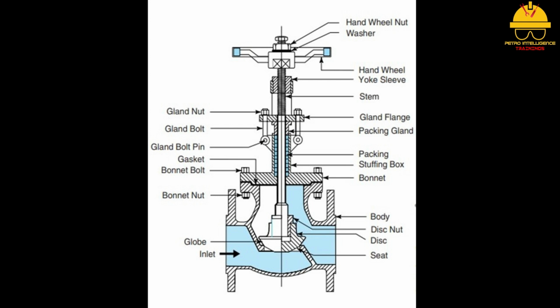The seating area comes in four designs: cone-shaped, beveled flat surface, O-ring or washer, and tapered or needle-shaped cone. The seating area is where the flow control element closes against the body of the valve to stop flow. The seating area can be replaceable or fixed. Seats must provide a clean mating surface to the flow control element to seat properly. The seat can be fabricated or cast as part of the valve, press fit, threaded, or welded into place. High temperature and high pressure situations may require a threading and welding combination.